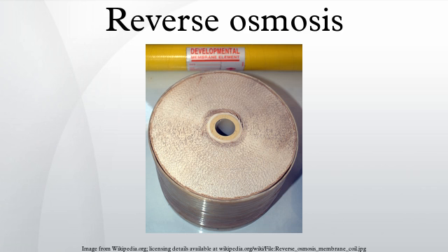In the normal osmosis process, the solvent naturally moves from an area of low solute concentration, through a membrane, to an area of high solute concentration. The movement of a pure solvent is driven to reduce the free energy of the system by equalizing solute concentrations on each side of a membrane, generating osmotic pressure. Applying an external pressure to reverse the natural flow of pure solvent, thus, is reverse osmosis.